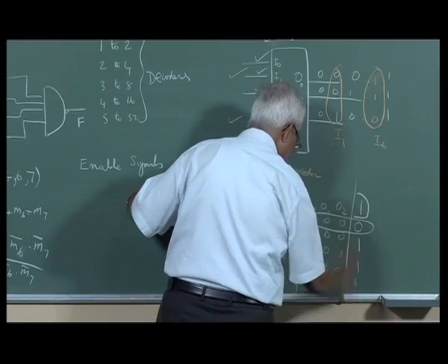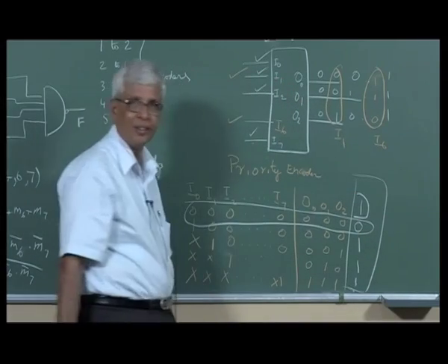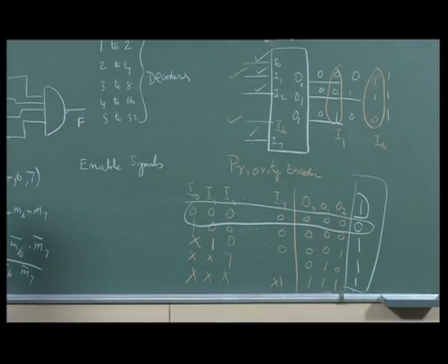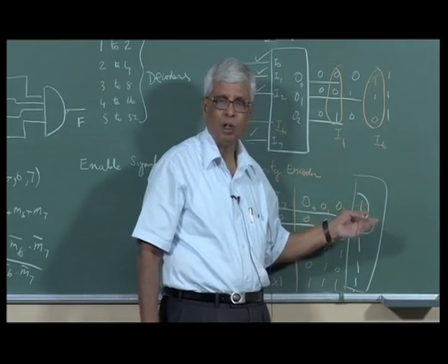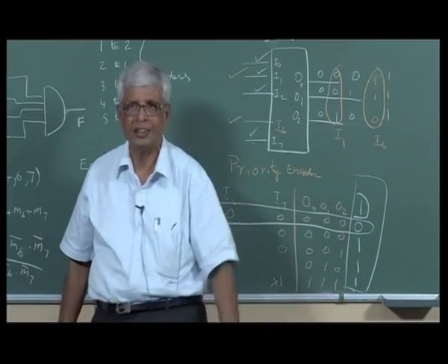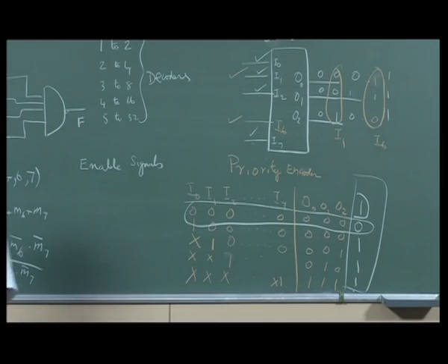So, looking at this D signal output, this enable is an input whereas this is an output, that is the only difference. What you said is right, but instead of enable as an input signal which you use in a decoder, we will use D as an output. This output D will be 0 if no input is present, and for all other input combinations 1 to 7, D will be 1. From there you can know.